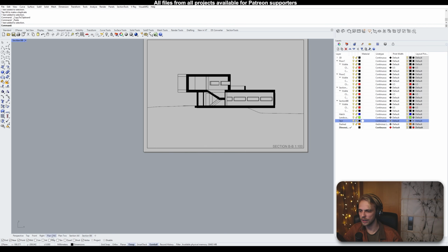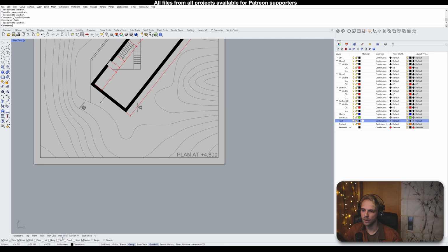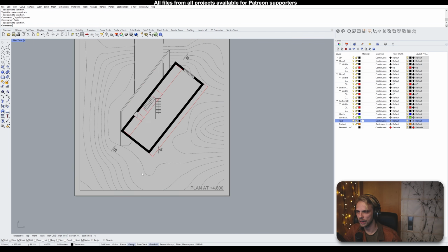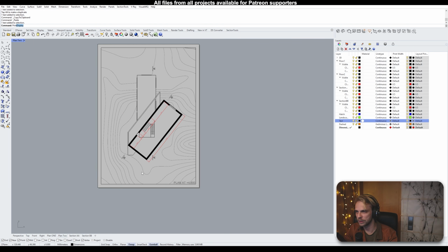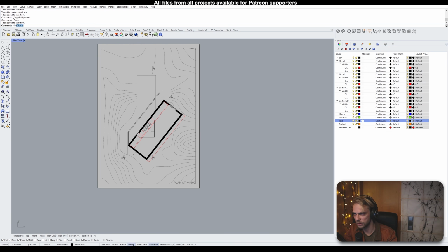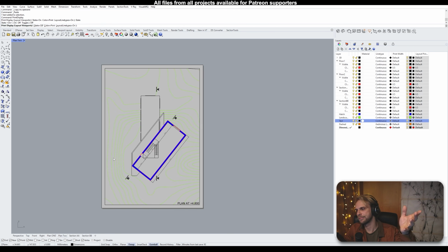Now, how do you get a drawing, like a PDF drawing out of here? Well, all you need to do is just Ctrl P. It doesn't matter in which view you're at. Ctrl P or type in print. By the way, to get rid of the print display, you type in print display again and choose state off. And it's going to show you the original colors, or, you know, the working colors. It doesn't matter if you're in print display or not.